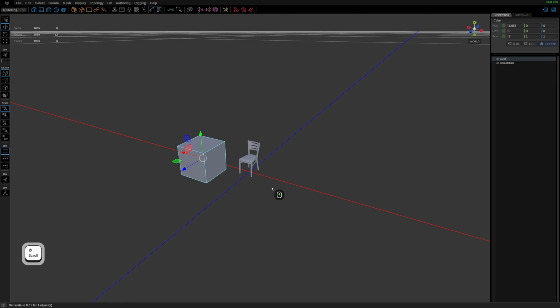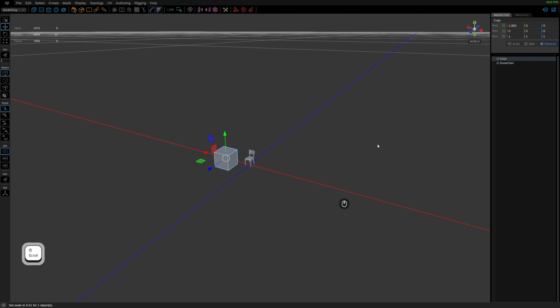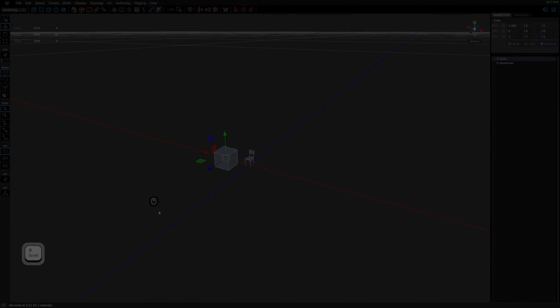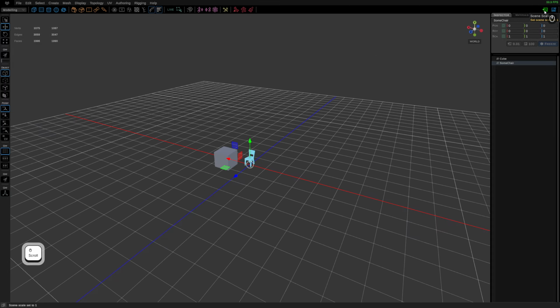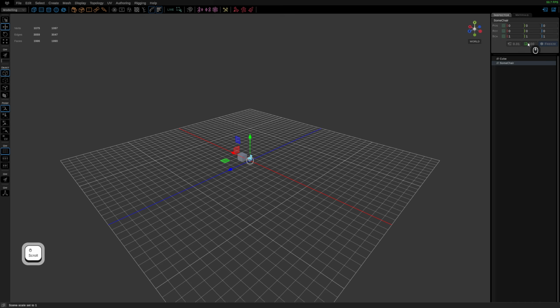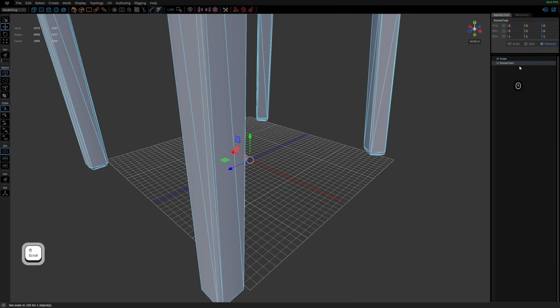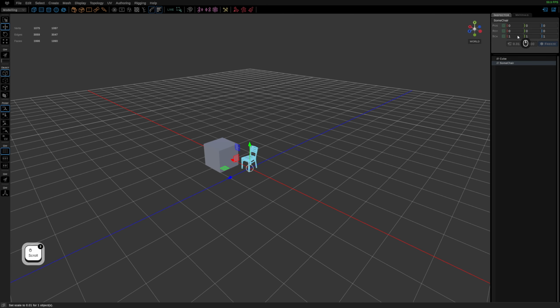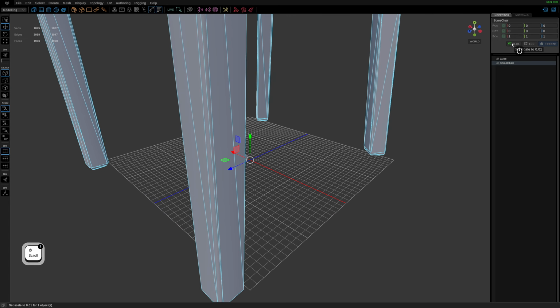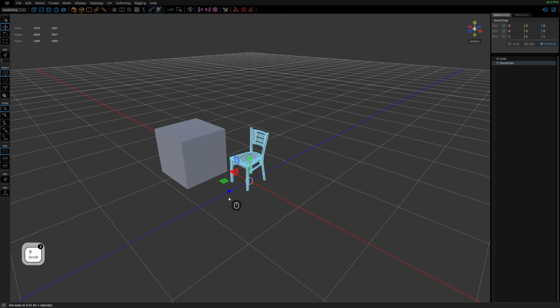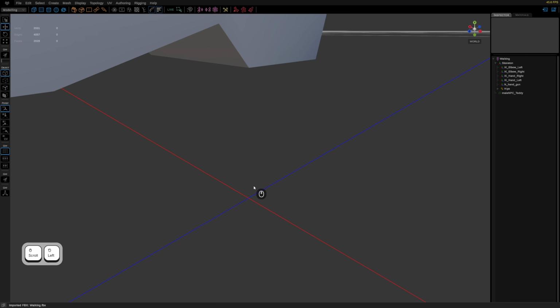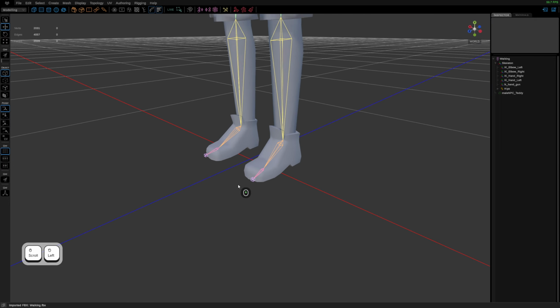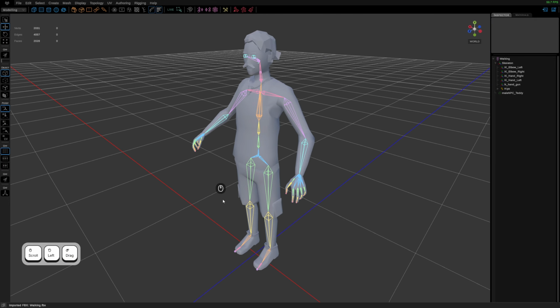So the scene is currently in a 1 centimeter scale. We can change this by simply clicking this button and everything is back in order. This button brings the object back up and this button brings it back down. Of course, you can do this manually and then freeze the object, but we provide a one-click solution. Easy. The issue becomes more complicated when a rigged model with animation is already in that scale.